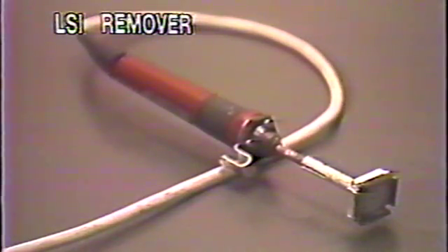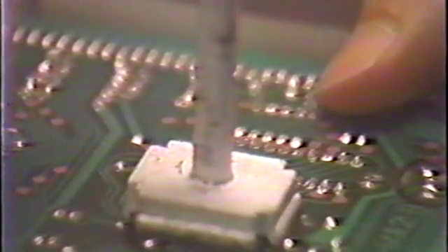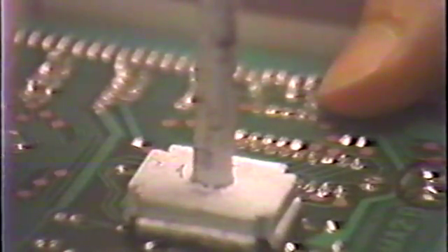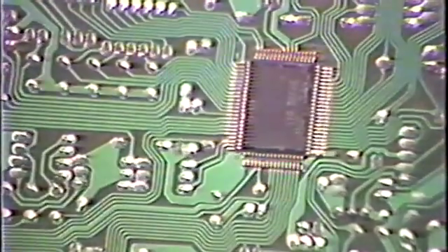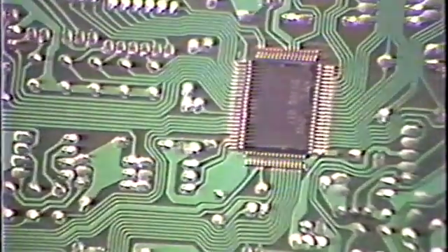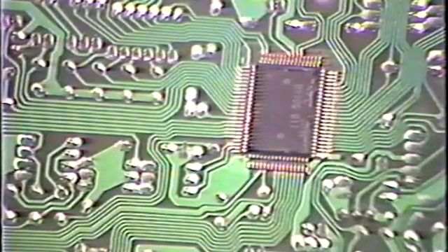This is a soldering iron used to remove soldered flat package LSIs. Just melt the solder with the tip, applying the LSI remover from the top, and remove the LSI by twisting the iron carefully. In some cases, LSIs are coated with an adhesive to prevent shorting due to condensation of moisture during low temperature tests in the factory. This adhesive can also be removed with trichloroethane.